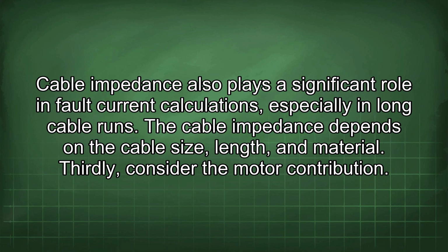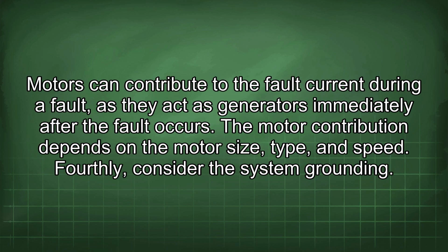Thirdly, consider the motor contribution. Motors can contribute to the fault current during a fault, as they act as generators immediately after the fault occurs. The motor contribution depends on the motor size, type, and speed.